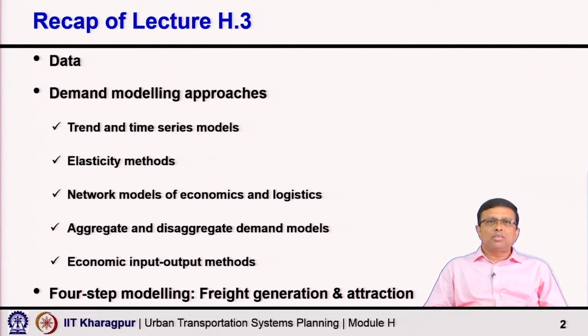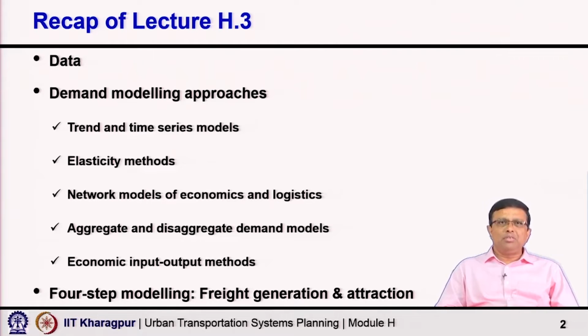Then we discussed various demand modeling approaches, namely the trend and time series models, the elasticity method, network models of economics and logistics, then the general categories of models like aggregate models and disaggregate models, and also the economic input-output methods.